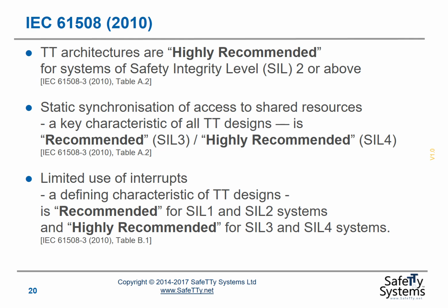We've seen that TT architectures are supported in various international safety standards. For example, they're highly recommended in IEC 61508 designs for systems of safety integrity 2 or above. And there are various other supportive statements in this standard that can help when developing a safety-related design in compliance with IEC 61508 using a time-triggered architecture.